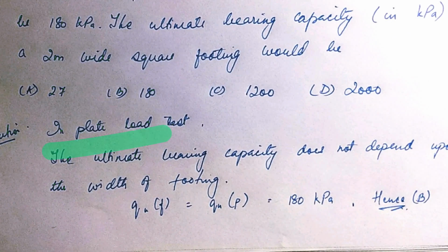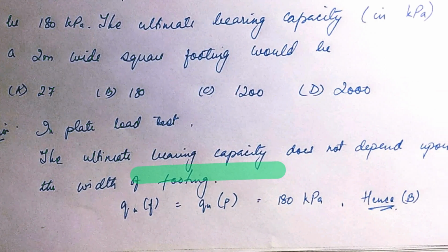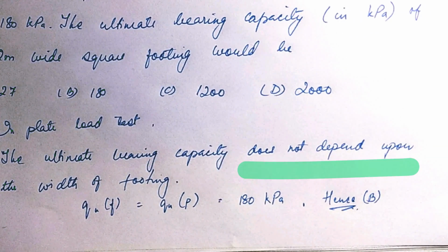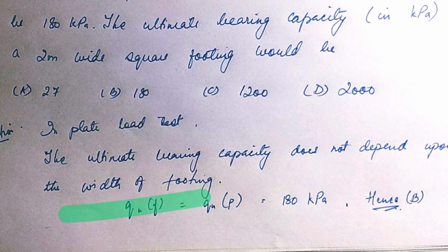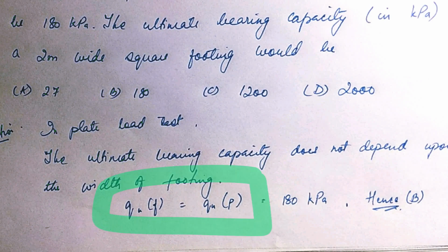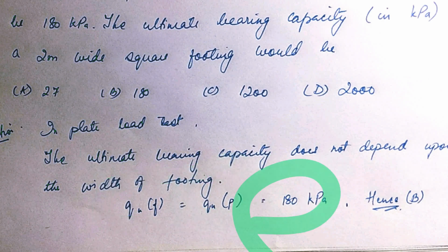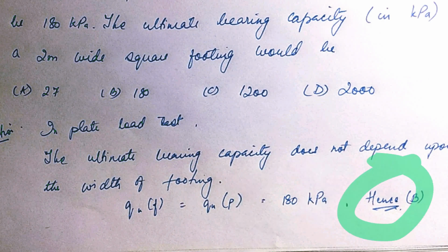In a plate load test on clay, the ultimate bearing capacity does not depend upon the width of the footing. We have already studied that q_uf is equal to q_up, and q_up is given to be 180 kPa, hence your answer is going to be 180 kPa.